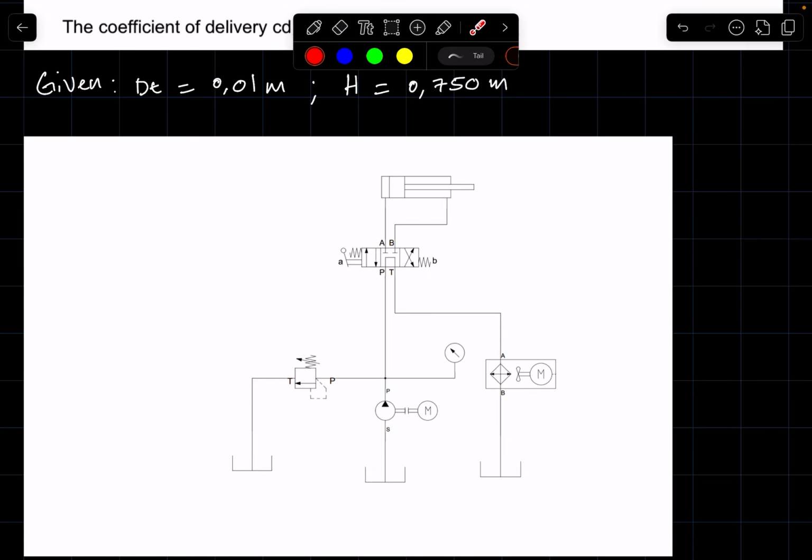loop hydraulic system is, water or the fluid is drawn from the reservoir. It does the work, and then on its way back, it is drained back into the reservoir. Because the fluid gets drained back into the reservoir, that is why we consider that an open loop system.